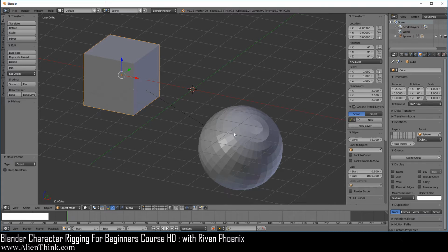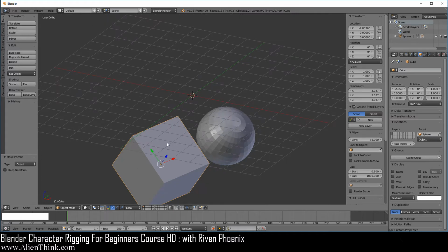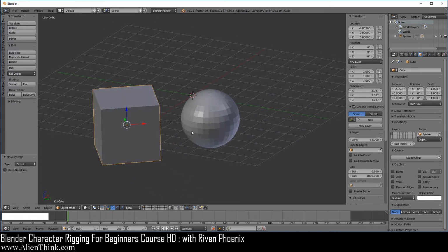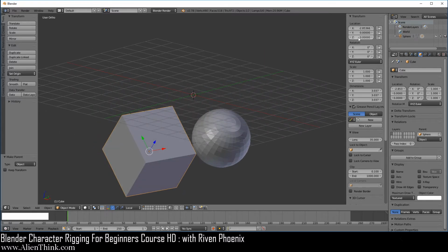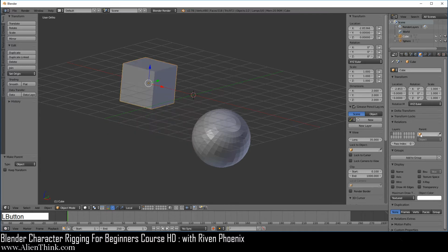Now notice what's going to happen over here. I'm going to switch this to local over here. Now when you click over here and go ahead and select object, notice that the child is now taking on the rotation and scale of its parent. You see how this is working now? When you click it, it's not going to show this, right? It's not supposed to, because when you X this out, it's just going to move back the way it is. Okay, so that's actually what's happening here.